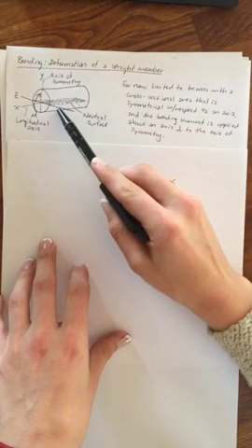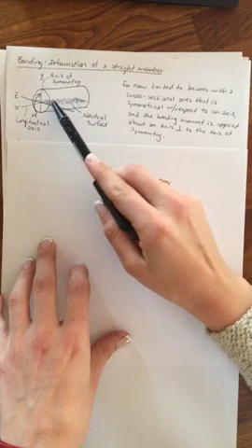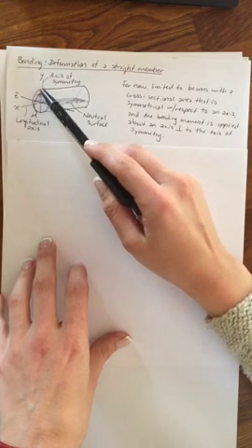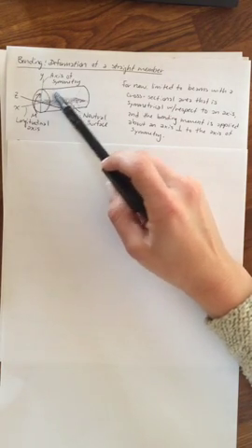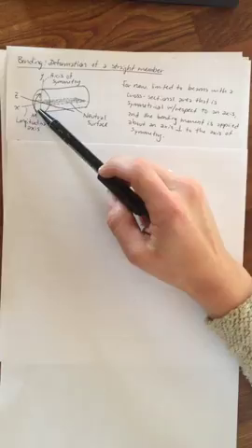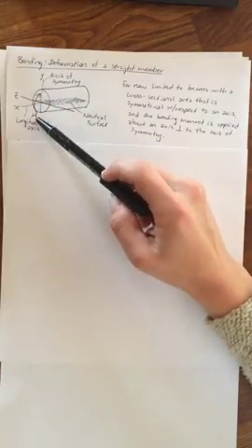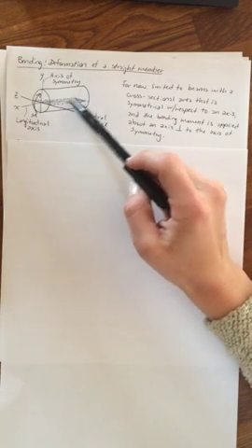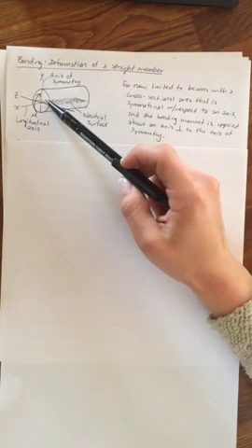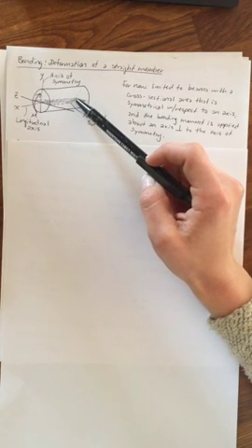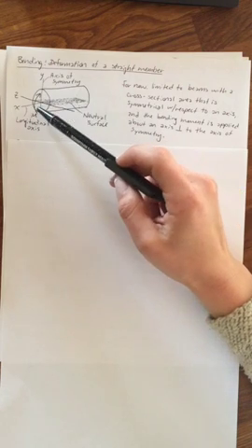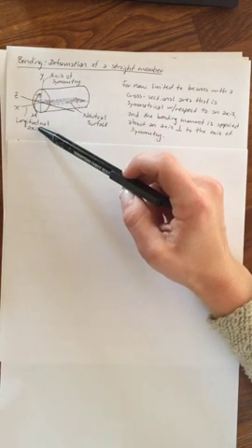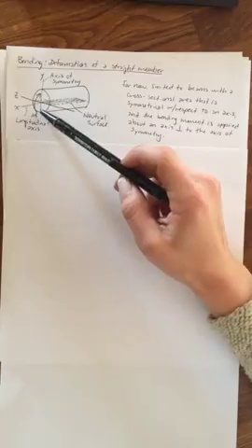So this is the diagram we're going to keep in mind where we have a neutral surface, which means above in the positive y, when a moment's applied, compression will occur, and then in the negative y, tension will occur. And this plane here is indicating where nothing is happening, so the lengths of these fibers would stay the same. And we call this the longitudinal axis, which the moment is going around, and then y here is our axis of symmetry.